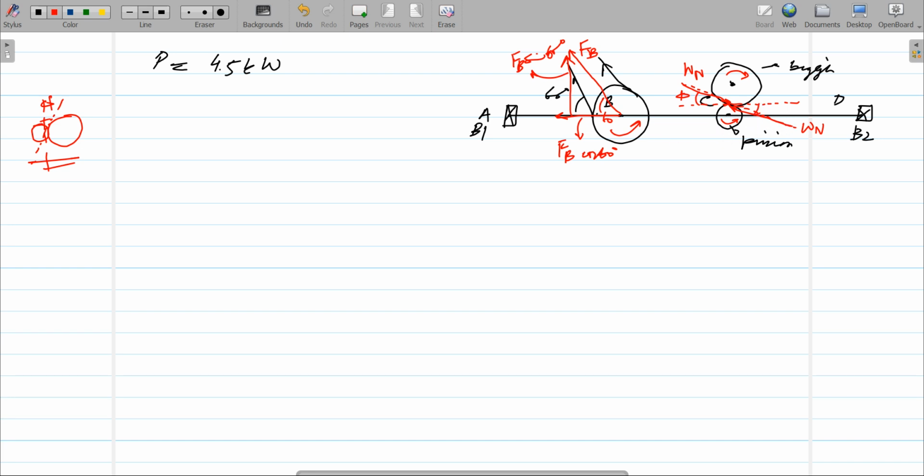So WN, and we have the pressure angle here also. So we have two forces, one is this and one is this. The force that is tangent to this circle is called WT, the tangential force, and the one that acts radially, towards the radius, is called WR. Similar is the case here, so this is called the action triangle. So we have a similar triangle here.